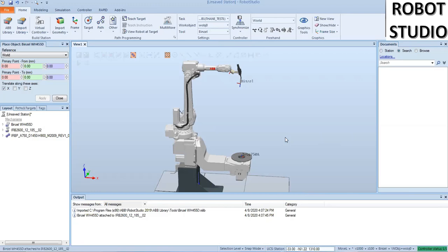and you wanted to program parts on that again, all you have to do is load that fixture back up, make sure the work object is correctly defined, and then you're set to go. You're not constantly reteaching from scratch, and it brings the points in really close on the real system. This also helps if you have to decommission a robot and put it in another location. You aren't having to do major touch-ups on all your intermediate points. If you do the work right up front, all you'd have to do is reteach those work objects, and your parts should come in as they did in the old system.